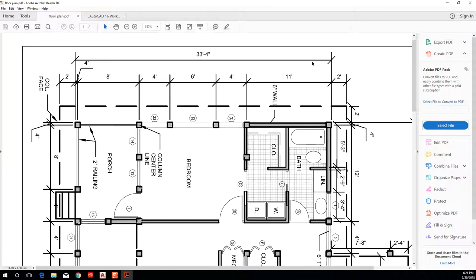It's an evolution, right? But when you hand draft, you control your line weights, or the thickness of your lines, with a pencil. When you draw thick lines, you get out a big thick pencil and draw thick heavy lines. When you want to draw thin lines, you put that thick pencil away, bring out a thinner pencil, sharpen it, and use it to draw thinner line weights, okay? Some pencils create thicker and heavier lines, and some create very thin and very light lines. That's how, when you were hand drafting, you could control what are called your line weights with pencils. The term line weight is the thickness or the thinness of a line, okay?